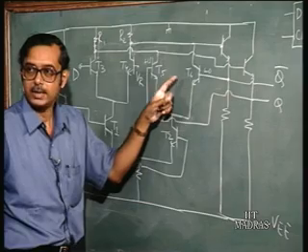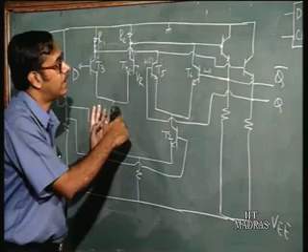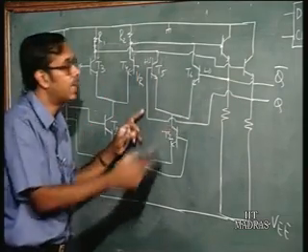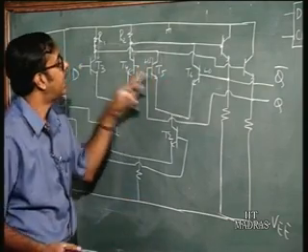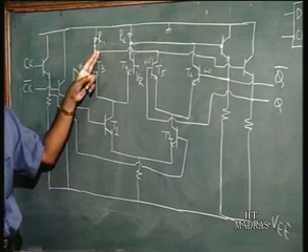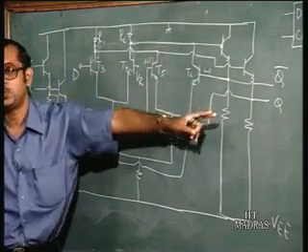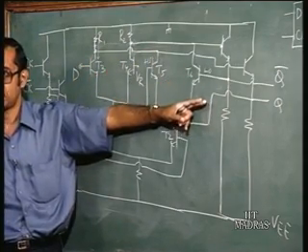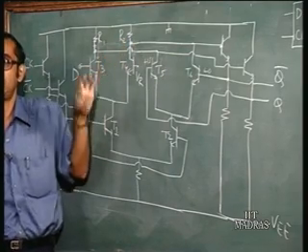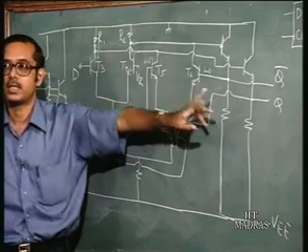One of the inputs is high and the other is low. So, if suddenly the clock goes low, the control is transferred to this part of the circuit, the right hand side part, and here the inputs are such that the currents continue to flow in the same resistance. If the current was flowing through R1, it will continue to flow in R1, and so the output really does not change. If current was initially flowing through R2, when the clock changed from high to low, it will still continue to flow through R2, and so the output does not change.